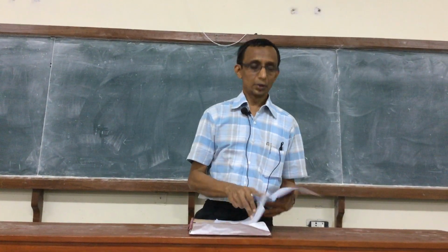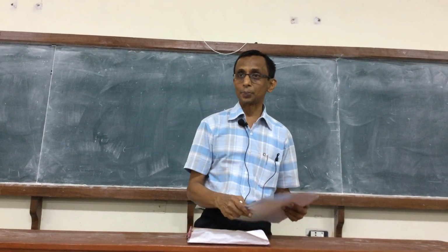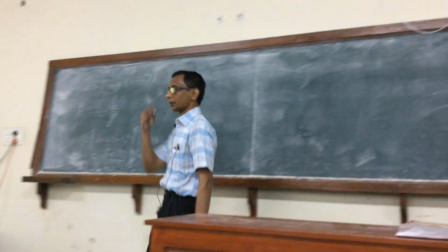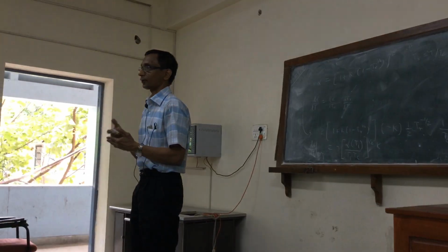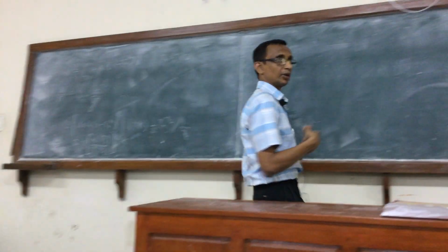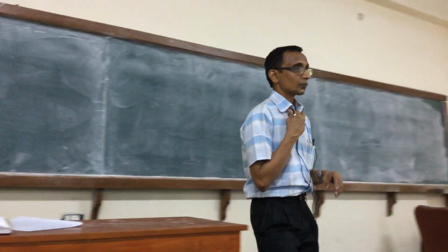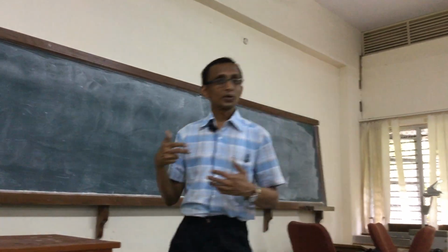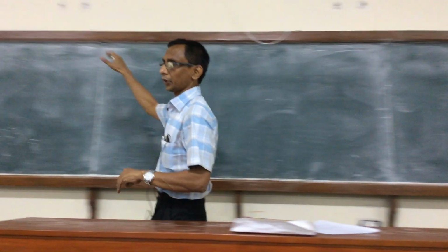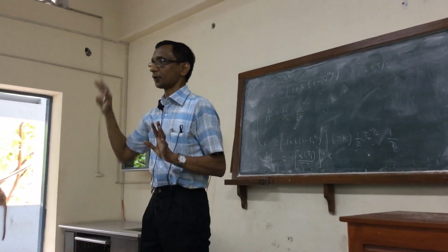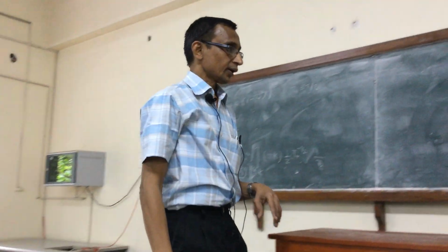Because I'm going to move on to the next important topic, that of calculating the saturation pressure. So far we have seen the departure functions are there, and we can calculate what is happening between two states as long as there is no phase change. The moment you have a change of phase between any two states, we need to know how to calculate. For example, if there is an enthalpy change between two states, and there is a change of phase between. So we are talking basically about working in the gas phase and then moving to liquid phase. We are not going further down into the solid. We restrict our attention to that first.